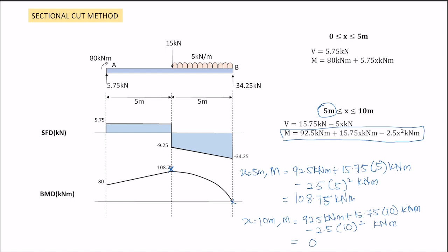Okay, so in this case, can you get the value at any point here? Yes. For example, if you want to get 1 meter, what is the bending moment value at 1 meter length of the beam? Or you want to find out the value at this point, or here, any point. As long as you know its length, you can get the value, because you can put it into the equation and get the exact value of the bending moment at a certain point.